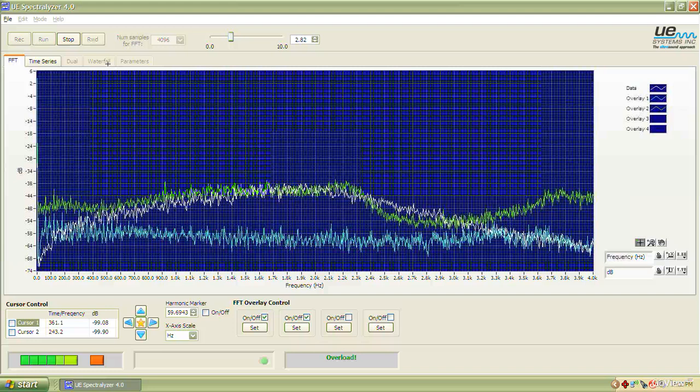All right. Under the waterfall analysis, a few things to show here. This is a little new to us. You may be used to it, but let's play it first off, and we'll talk about it. Now, again, this is giving us a 3D view, but to change any of your axes, you can't click on it like you can the other graphs. So what you need to do is frequency axis ranges: minimum, being the left-hand side here, is 10. That means 10 hertz, and maximum would be 2000 hertz. If I wanted to spread that out or zoom in, I would simply change the number in here.